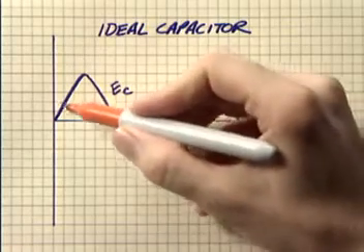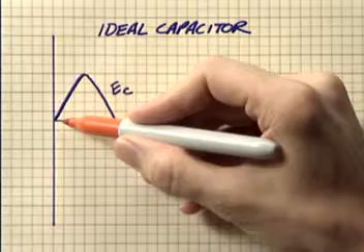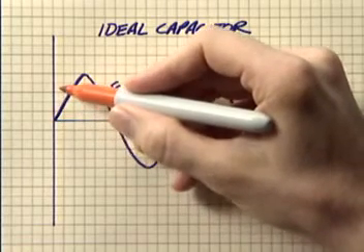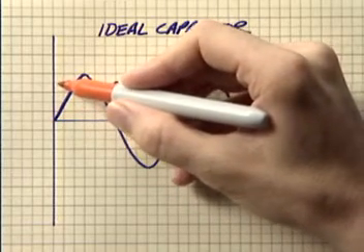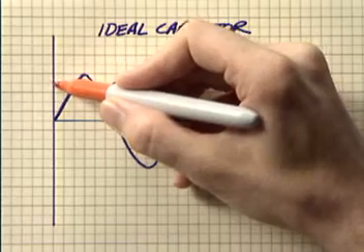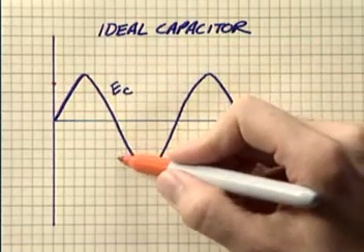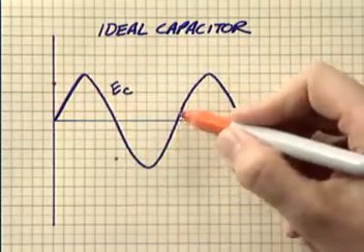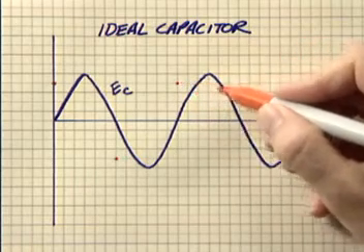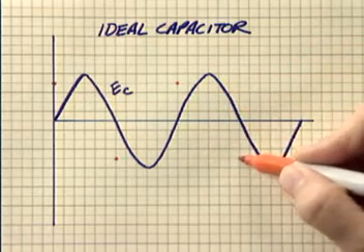Since the greatest rate of change in a sine waveform occurs when it passes through the baseline, then the maximum capacitive current will be at these points. Place a dot on the graph to mark each of these points. A different amplitude has been arbitrarily selected for the sake of visual clarity.